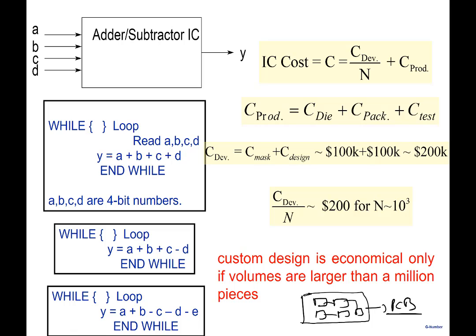There's a register IC available. There are muxes available. You can take all these ICs, connect them up on a PCB and make your design. That you could do. But what is the price that you have to pay? The area becomes larger. It dissipates more power. Note that on a PCB, the wire lengths are longer. It becomes slower.